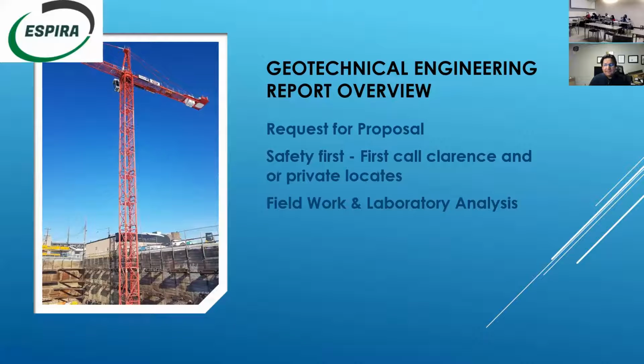And then the geotechnical engineer designs the field work. For example, based on what the land would be used for, they say, okay, we'll do, for example, 6 boreholes to 9 meters. We're going to install 2 standpipes to 9 meters to monitor the groundwater table. They also design what type of lab tests they'll be doing. For example, basic tests like moisture test, Atterberg limits, hydrometer test, etc.